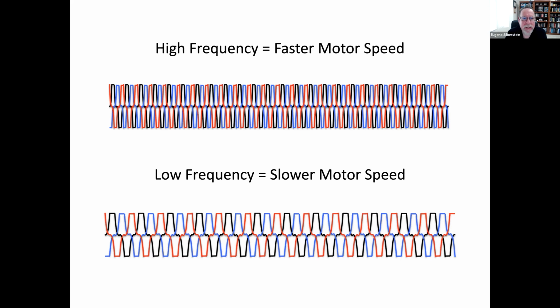Well, why is this important to us? Well, when we have ECM motors, blowers, that are feeding air through an air distribution system, that fan is going to ramp up if the duct system is undersized. Think about it: our duct system is smaller, more resistance to airflow. That blower is going to ramp up in speed to provide that constant airflow.